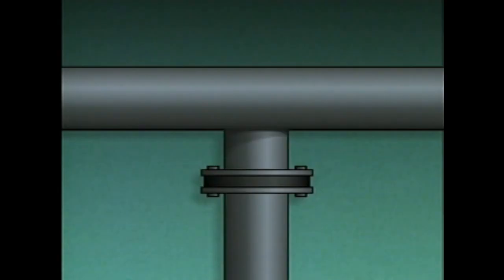A rupture disc is one type of device that's used to relieve excess pressure in fluid systems. A rupture disc is designed to rupture or break when fluid pressure exceeds a certain value. When the disc breaks, fluid passes through it and the excess pressure is relieved. This illustration can help explain how a rupture disc works.